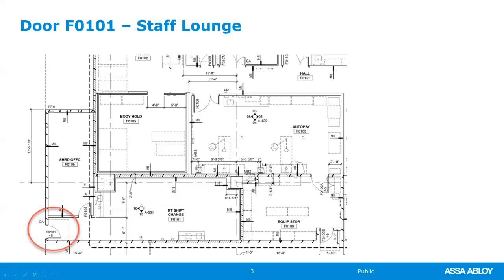The other thing I want to point out, think to yourself for a second, does this lock that goes on this door that works with this card reader, does it need to be fail safe or fail secure? Think about it for just a second. As long as you have free egress from this staff lounge to get out, which the inside handle of either a fail-safe or fail-secure mortise lock would allow you to do, either way, I can exit this space.